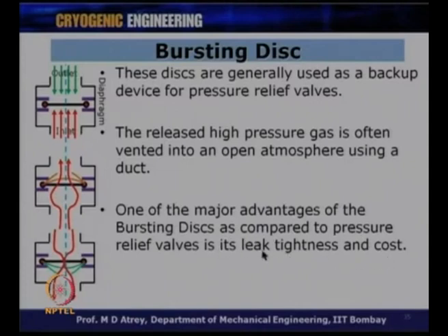Leak tightness can be of a very high order as compared to the mechanical pressure relief valve, and its cost is very low as compared to pressure relief valves. Therefore, the replacement of a burst disc is not very problematic.